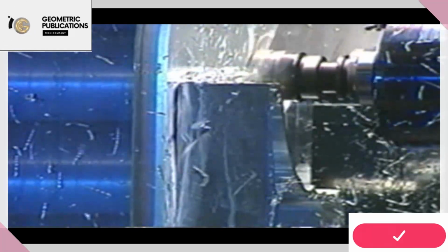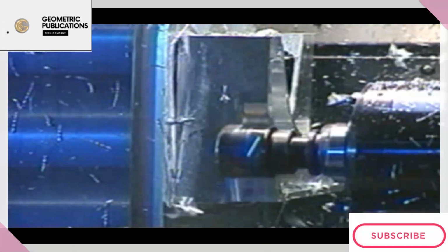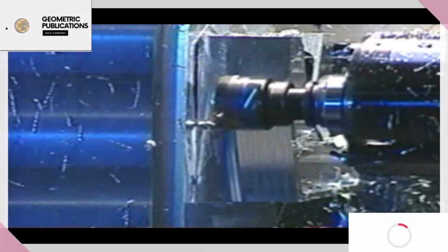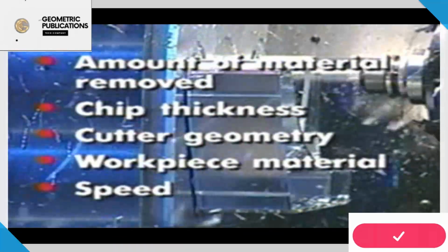Efficient milling also requires horsepower considerations, so that the milling cutter makes the best use of available machine horsepower. 1 horsepower can remove 1 cubic inch of steel per minute or 4 cubic inches of aluminum per minute. To mill an aluminum workpiece at the rate of 40 cubic inches per minute requires 10 horsepower. The power required for an operation varies with the amount of material removed, average chip thickness, cutter geometry, workpiece material, and speed.